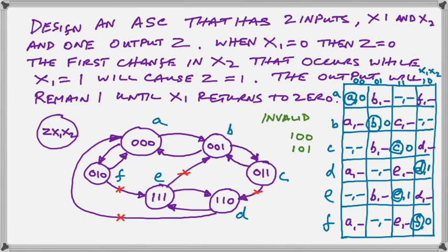The primitive flow table has one stable state per row, and it also indicates the manner in which we may move from that stable state to the next state. So the contents of the primitive flow table completely correspond to what is shown on your total state diagram.